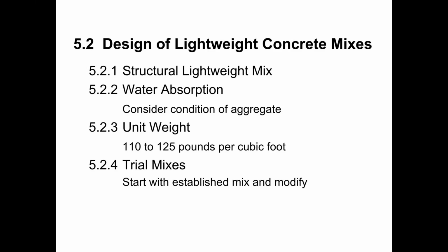All right, just like with regular weight concrete mix design, the real work in dialing in the mix comes through the trial batching process. If the tables for the regular weight mix design got us just in the neighborhood of where we need to be, then the tables for the lightweight mix design just maybe get us into the county that we need to be. They're less precise than the other tables that we've been looking at, and so there is a lot more work to be done during the trial batching process with the lightweight mix design than even with a regular weight mix design.